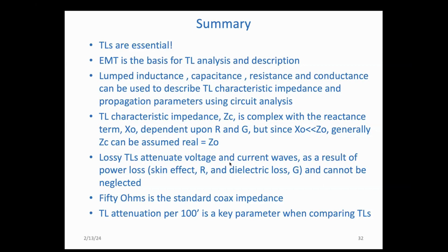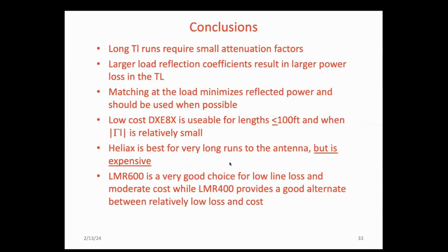50 ohms is the standard coax impedance, as we stated before. And the attenuation per 100 feet is a key parameter when comparing. Next slide, please. Long runs require small attenuation factors. I think that's obvious. Larger reflection coefficients result in larger power loss.